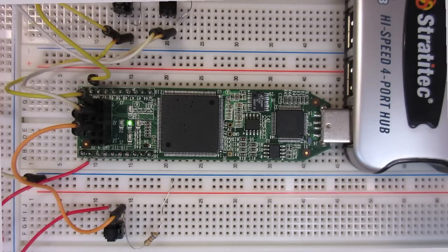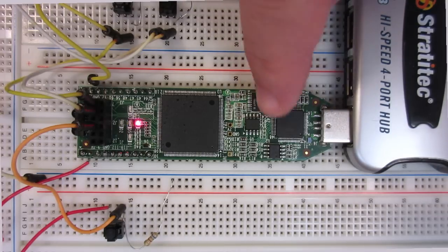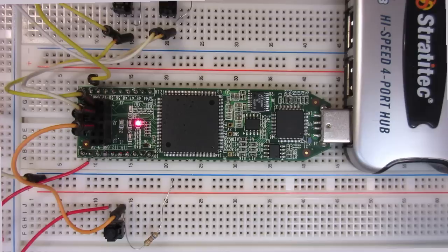Here's the actual iCEstick on a breadboard. I'm using a USB hub just to power it, and I soldered some headers on the side for power and ground. The inputs are up through the PMOD connector on the top. There's no PC, but the configuration flash right about here is holding the FPGA's configuration. You can see I have a reset button on the bottom, and the A and B buttons are up near the top. The switches are connected to 3.3 volts, and I put some pull-down resistors to ground.